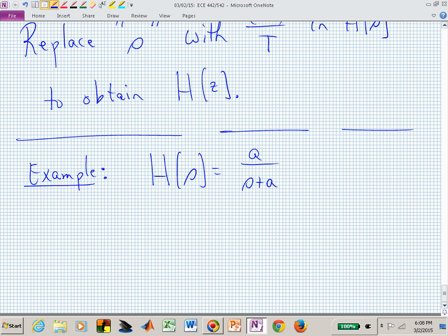What I was hoping you would do is you would say, that's a first order system, right? It has a denominator with one factor, one power of s. It's first order. And I hope that after today's class you go, I could actually kind of think about that in terms of a Bode plot. That's actually just a low-pass filter.